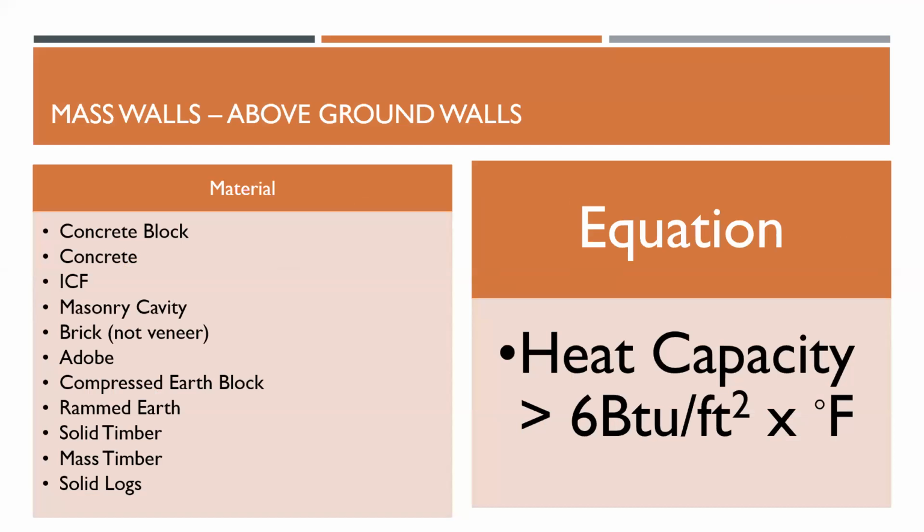Joe, we had another quick question come up on insulation. This attendee says they have had inspectors tell them when using 2x6 framing walls that they need to fill it up with insulation, which would be more than R13. Their interpretation is to use R13 as long as the insulation is held toward the interior of the wall. Is there something about that in the code? And she is aware of the exception for existing homes that don't have enough space for the required R value.